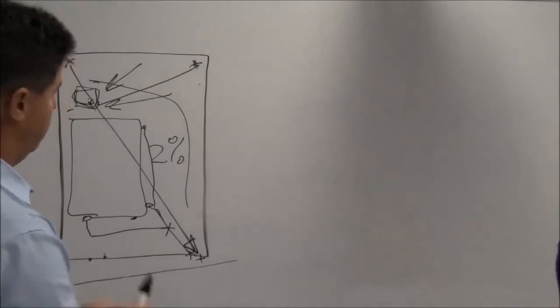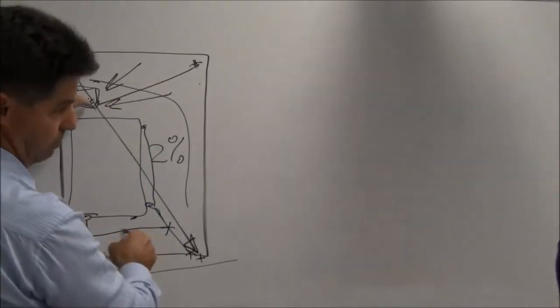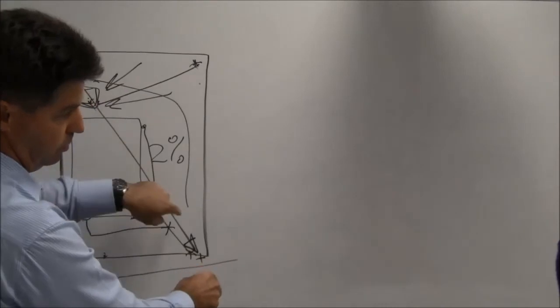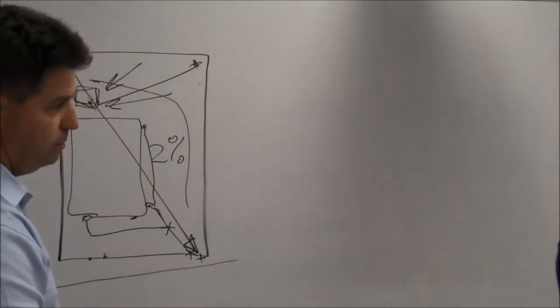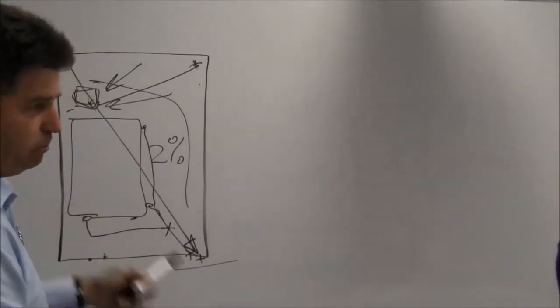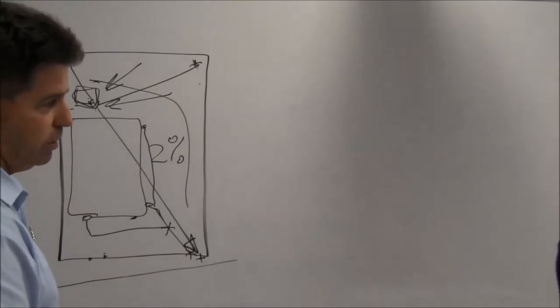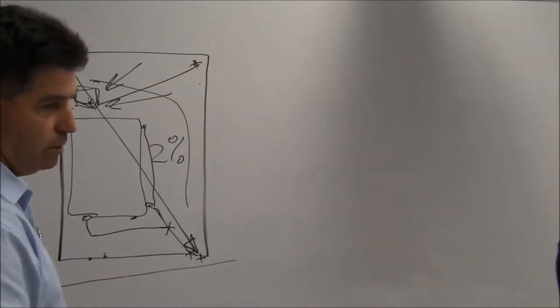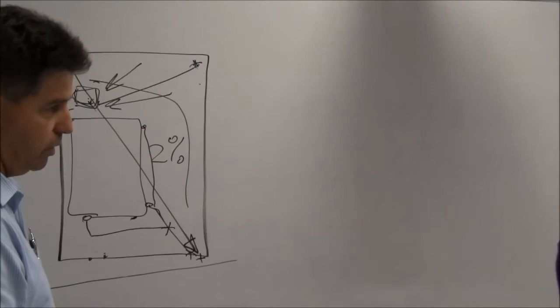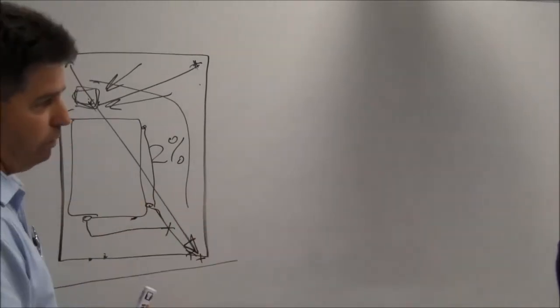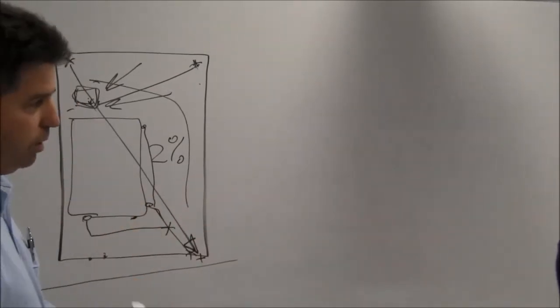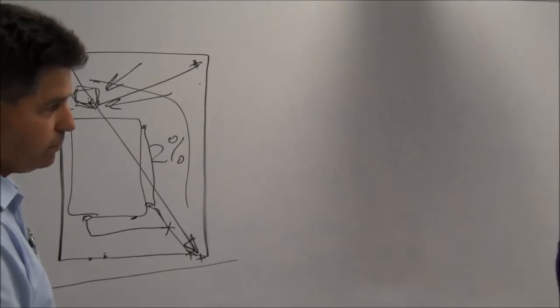Does that make sense? It's like if you threw a marble down here and threw a marble here, the marble here is going to get to the point quicker because the other is further away. But if you keep throwing marbles down, eventually they're all going to get to the same point all at once. So it's basically just a time measure for all the rain to be discharging through a pipe at a certain time, based on the worst case.